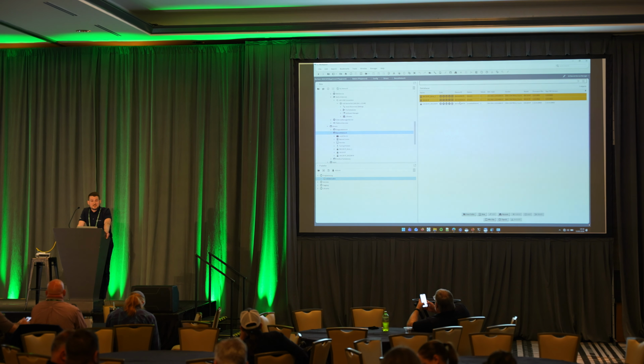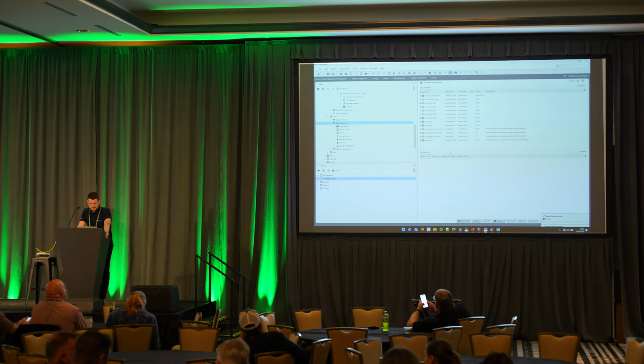All of our Nano Edge engine controllers, they're Niagara native. So upon the first connection, you can just discover the controller on the BACnet network. If you use Ethernet, you will just drop this extension to your BACnet device. This UAC28 IP, it has some points already on it. So you can discover it here. But we are going to connect over the USB now.